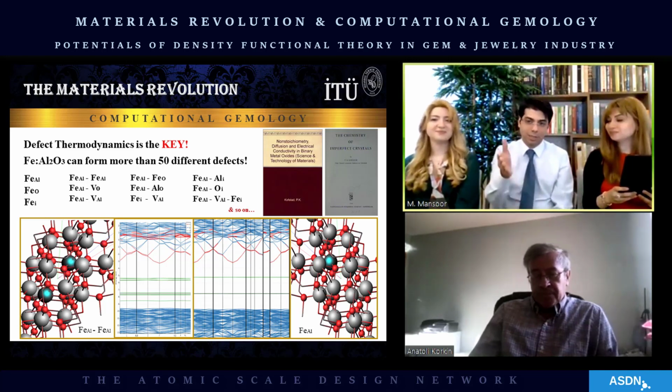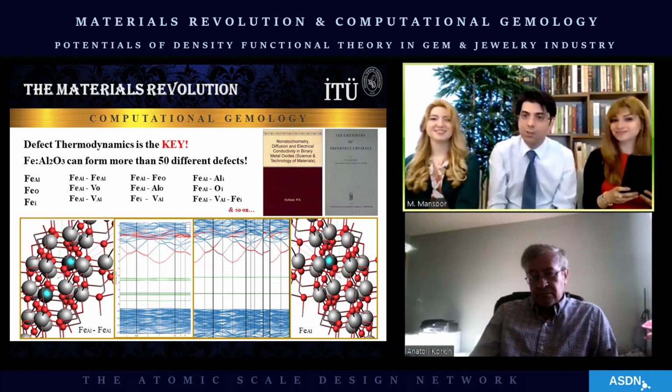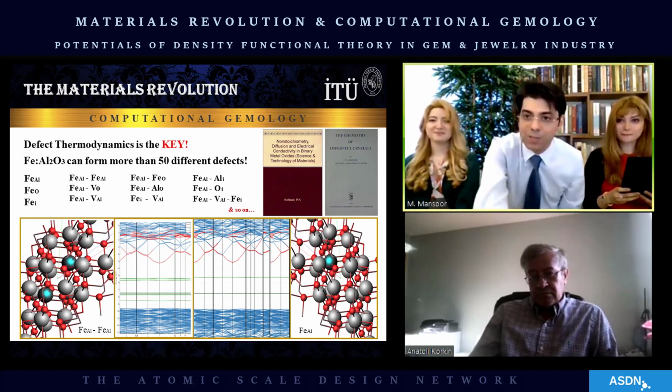And again, it's a beautiful example of how the defect is extremely important in the band structure of the material. So having a precise idea of the interactions between the stable defect, its optical transitions, and the defect thermodynamics, that circle. If we don't know that information, then we are pretty doomed if we want to do high temperature heat treatments on top.